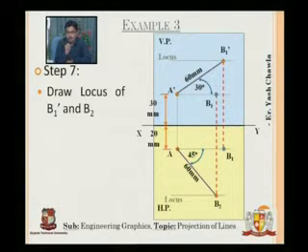So what I'm going to do now is, we will have this AB1. I will take the radius as AB1 and I'll draw an arc which will intersect this locus at some point. And similarly, I will take this A dash B1 and then I will draw an arc which will cut this locus at a certain point.